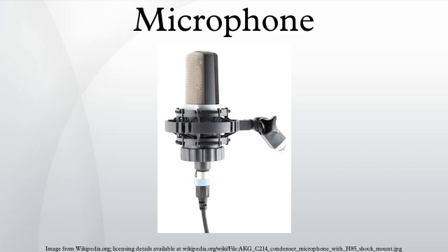A parabolic microphone uses a parabolic reflector to collect and focus sound waves onto a microphone receiver, in much the same way that a parabolic antenna does with radio waves. Typical uses of this microphone, which has unusually focused front sensitivity and can pick up sounds from many meters away, include nature recording, outdoor sporting events, eavesdropping, law enforcement, and even espionage. Parabolic microphones are not typically used for standard recording applications, because they tend to have poor low-frequency response as a side effect of their design.